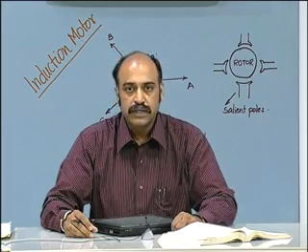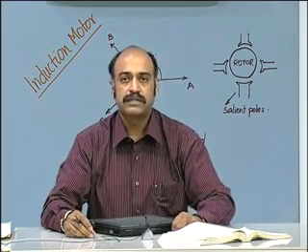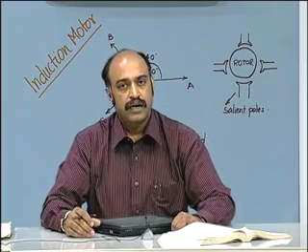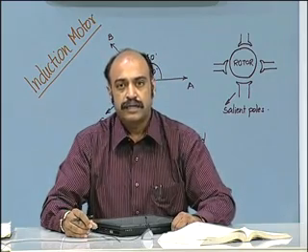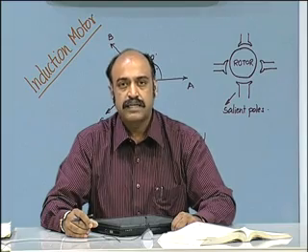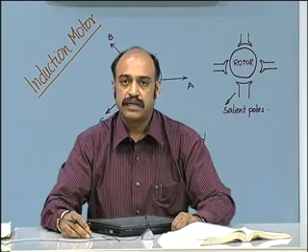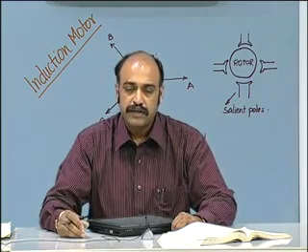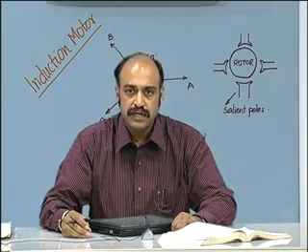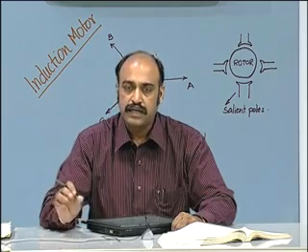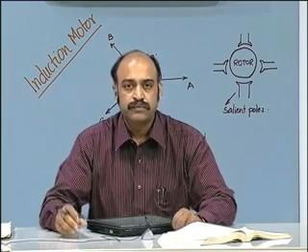And in the rotor again there are rotor conductors. There will be I square R losses in the rotor conductors, and minus that I square R loss, the remaining power goes to the mechanical shaft. If there are bearing frictions associated, some portion of that power goes there, and ultimately you will have the shaft power.